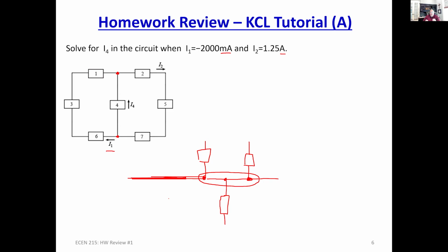I know it seems simple at first, and like, duh. When we write equations for nodal analysis, that is the number one problem I see, especially on tests. People will see a circuit like this and write an equation for this node, an equation for this node, and then a separate equation for this node. Technically you can do that, but it's effectively the same equation every time.